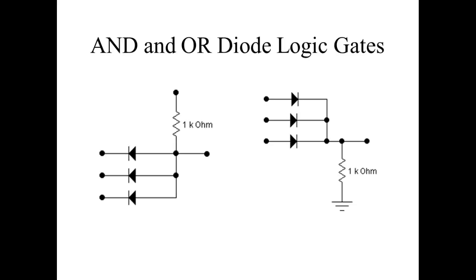Okay. You understand? What we did the other day is we set up a thing called a truth table. What's a truth table? It shows you the output for all given inputs. And this is binary, folks. So how many possible input combinations would this gate have? All I have to do is look at the number of inputs and raise 2 to that power. So 2 to the third means this gate should have 8 combinations.